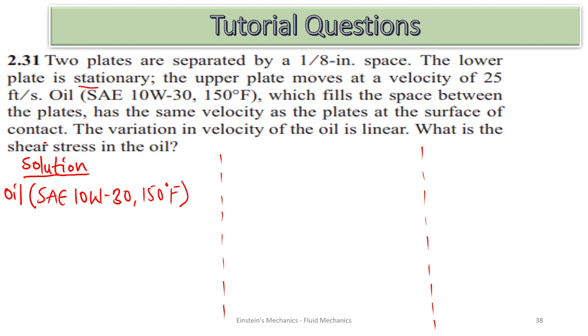And we are given the plates are separated by 1/8 inch. So the separation between the plates, which is the distance between the plates, is change in y. Remember the formula for shear, we are using change in y for the space between the plates, and that is 1/8 inch, which is also the same as 0.125 inches.